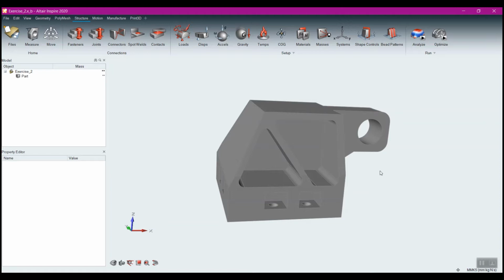It's like sculpting. A sculptor looks at a block of material and sees inside of it the part or the statue that they're looking to reveal to the world, and their job is to carve away the excess material. Topological optimization works the same way. You define the maximum amount of material that you can have, effectively determining what your design volume is, and you fill that with material.